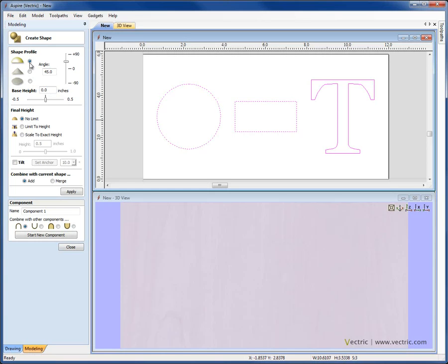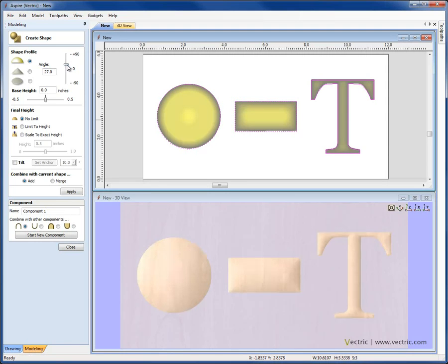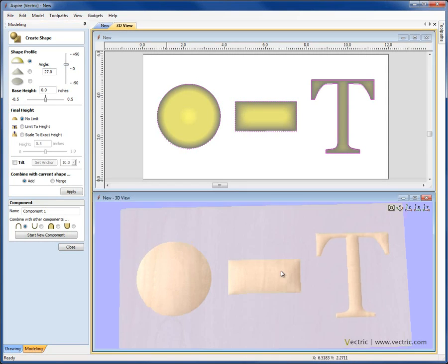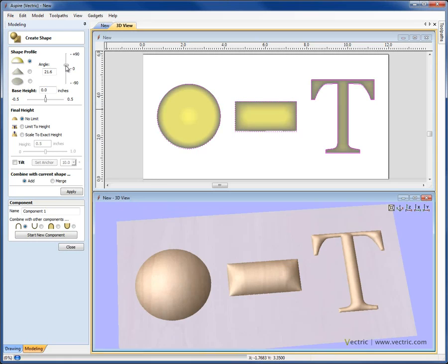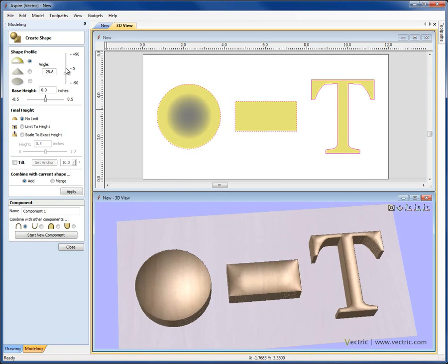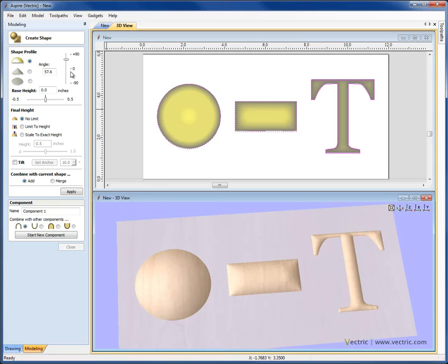So we said before we have the round, pyramid and plane shape. For the round and the pyramid shape, I'm going to be able to define an angle and the size of that angle, whether positive or negative. I can type in a value or use the slider. If I use the slider here, as soon as I let go, the software is going to update the shape that we have in the 3D view. This is essentially a dynamic menu, so as I make changes to this, you can see that it automatically recalculates and changes the shape based on the value that I've chosen with the slider there. As I said, it's also possible to type in a specific value, and you can apply that by hitting the spacebar on the keyboard.